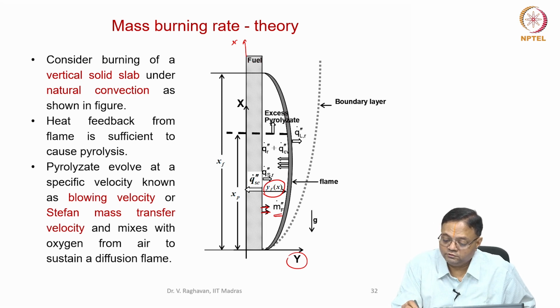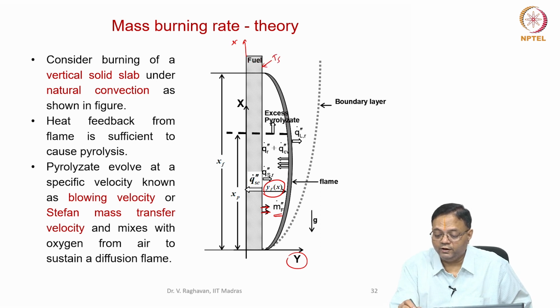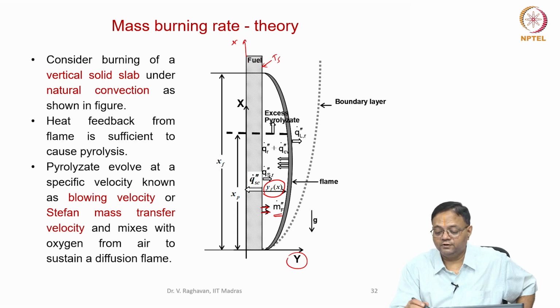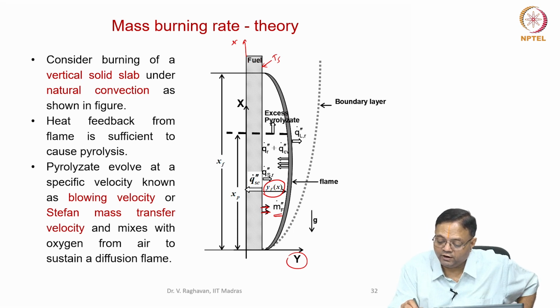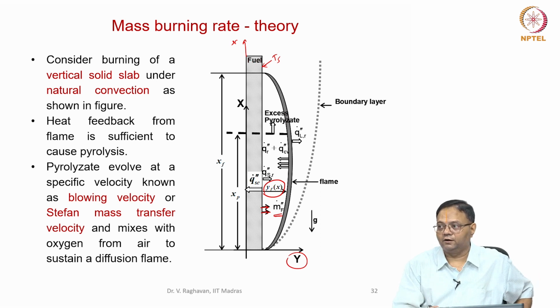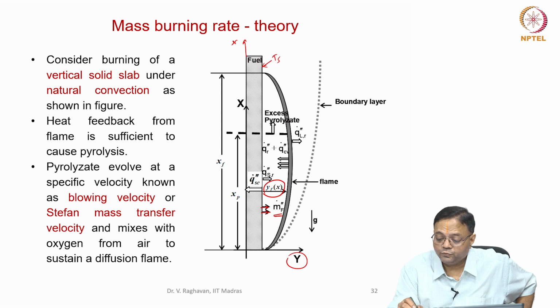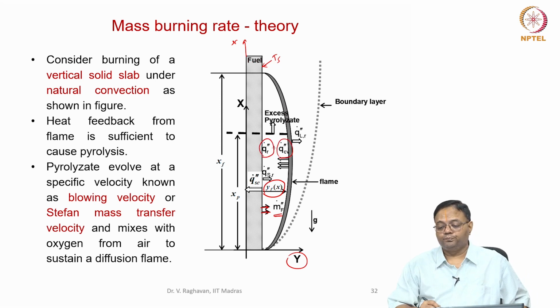Now, the surface has a temperature Ts, due to which there will be some radiation given out from the surface to the ambient, re-radiation, that is. Some amount of heat flux can be conducted, solid conduction. So, conduction heat flux can occur, and the heat provided by the flame to the solid can be due to radiation and can be due to convection, both.